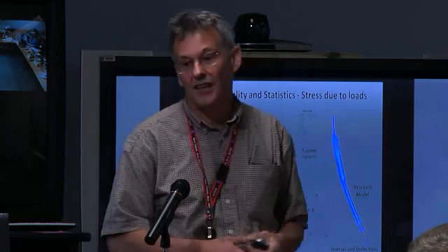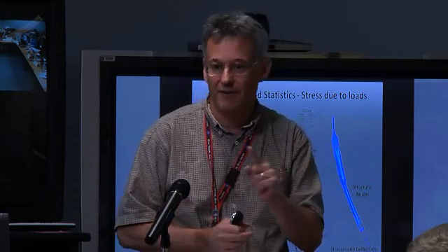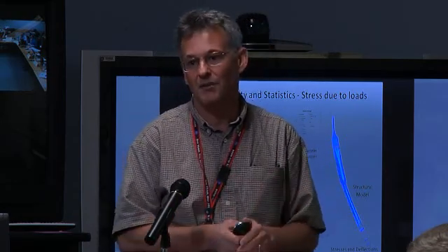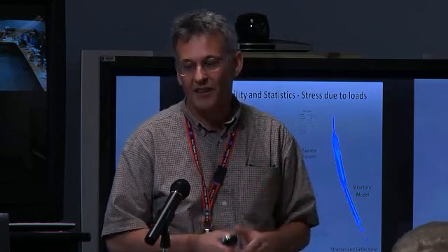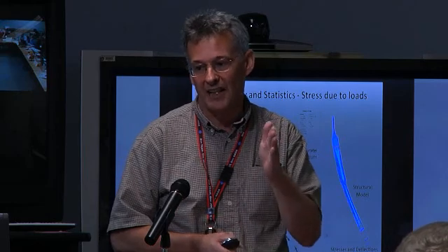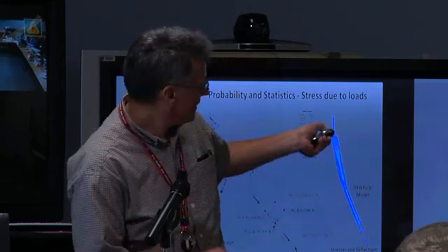Other parameter variations include engine performance. The engine may have a thrust of 100,000 pounds plus or minus a certain amount, and it can vary in there. So all these parameters that aren't 100% fixed, you understand what they are, an average and a distribution around that average, just like we had for the strength. And those are all inputs into a Monte Carlo simulation, in this case of controls.